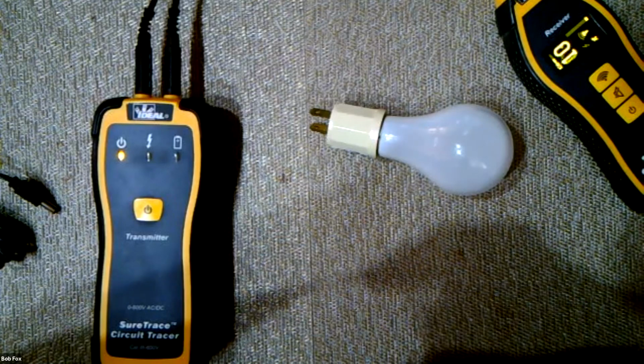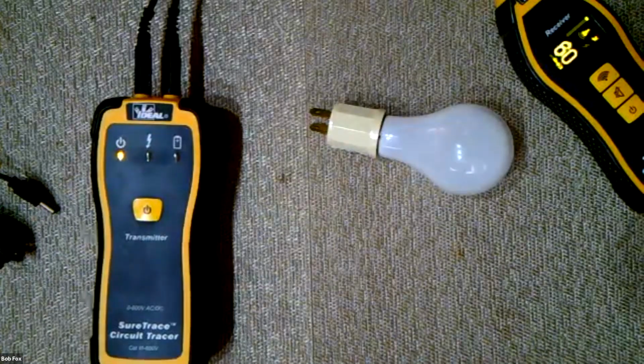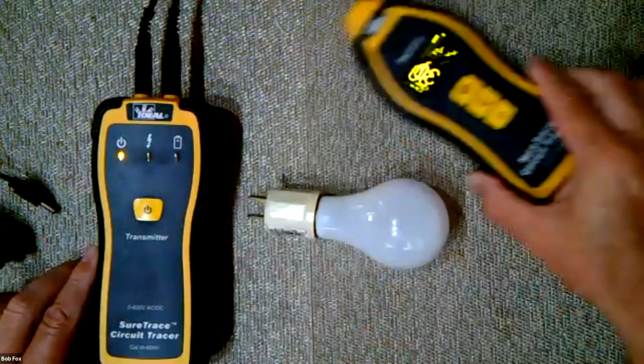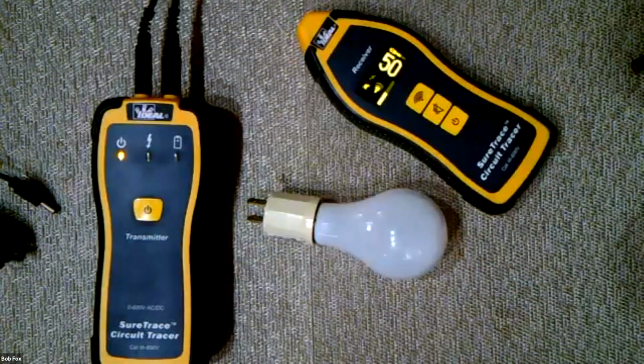And again, you would think with 2.5-inch galvanized pipe, the pipe happened to be 6 feet down. The substrate was sand and clay, so it was pretty clean. In that particular case, we were able to put a flag every so many feet, and when we went to dig with the backhoe, it was dead center on that particular pipe. But again, it's situational, right? Because Dave's talked a little bit about it, but it depends on the substrates. For example, if you're trying to trace a conduit in something that's filled full of rebar, there could be some instances where it's a little bit tougher, right? So again, it's situational, and a lot of it depends on the substrate.